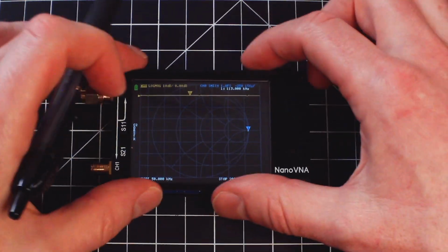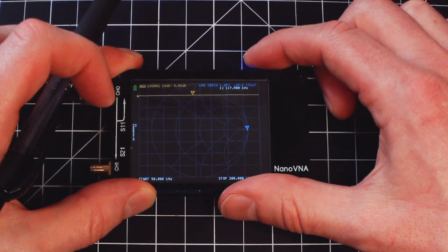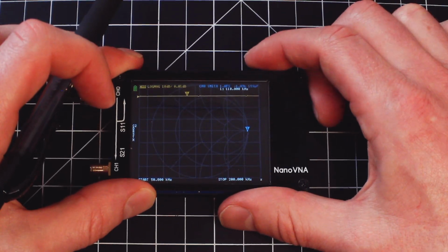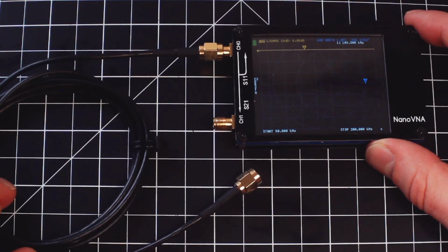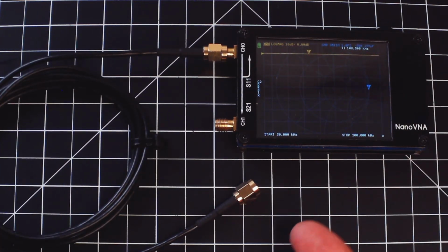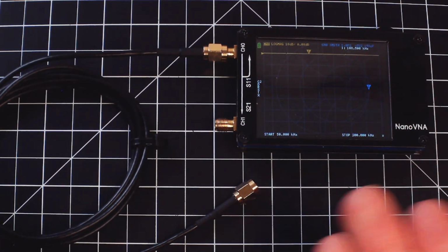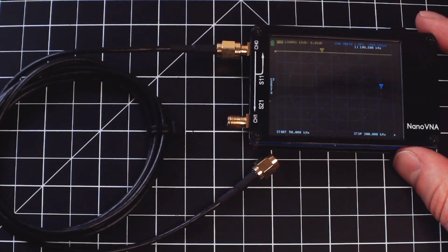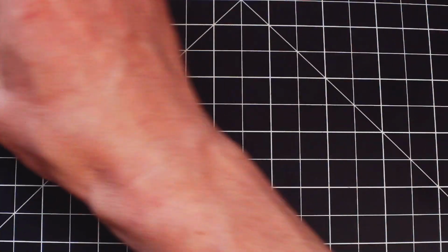Okay, and you notice also I can scan around in frequency and it just kind of bumps up and down by a couple of picofarad. So it's actually a very interesting measurement you can do, that your NanoVNA will act as a very strong and accurate capacitance meter by just reading any sort of lumped element at a low frequency.